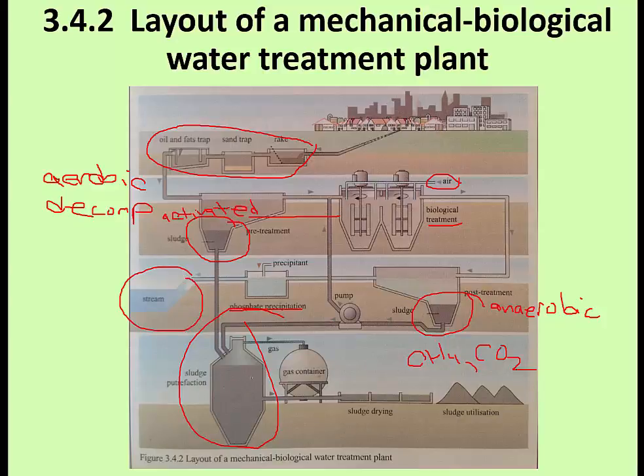You take your sludge down here, you break that down. You can collect your gases right here. Okay, you can dry this sludge, and now this is deactivated. Okay, I'm going to abbreviate that. So deactivated sludge can then be used as a fertilizer. It can be spread on fields. It has a high mineral content, it's good in nitrogen, it's good as a fertilizer at this point, and the biological activity has ceased in there, so it can be used as a deactivated fertilizer.